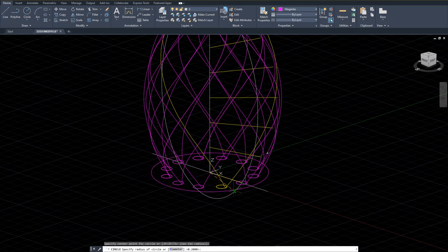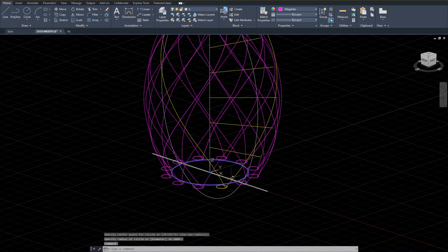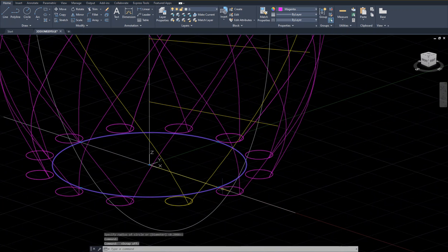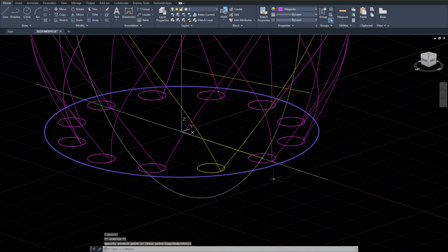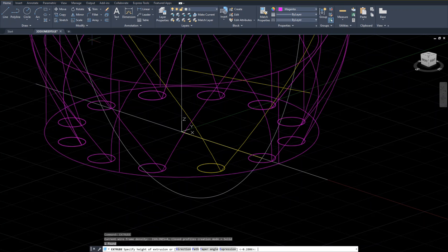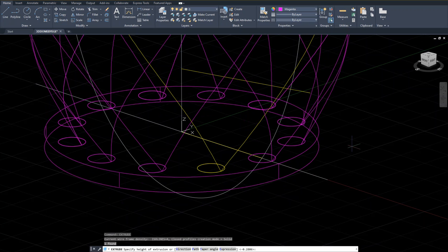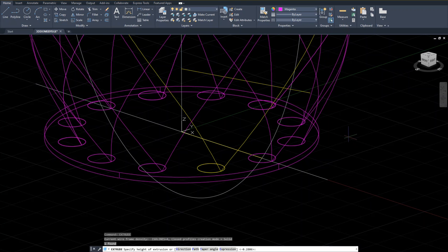Okay. Let me make a circle slightly larger than the bottom. Oops, sorry about that. Make the circle a little bit larger. I'm going to turn off object snap. Why is it happening? Sorry about that because I should know better. Okay, click. Very good. Now we're going to do some extrusion. Okay, downwards. How much? Very little, 0.1 or so. So the command is extrude. Sometimes you can type it, and that's the nice thing about AutoCAD. You can type, and how about minus 0.1?